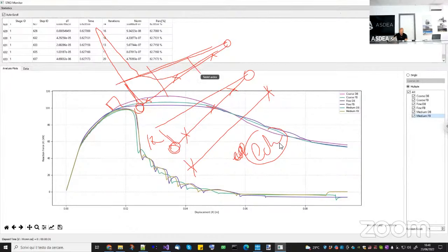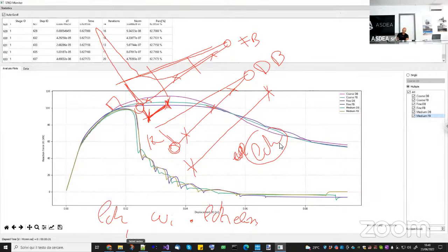So this one is the displacement-based, and this one is the force-based. For a force-based element, the characteristic length should be the length of the Gauss point, which corresponds to the weight of the Gauss point i times the length of the element, the LCH element. And this one is the LCH for the force-based column.